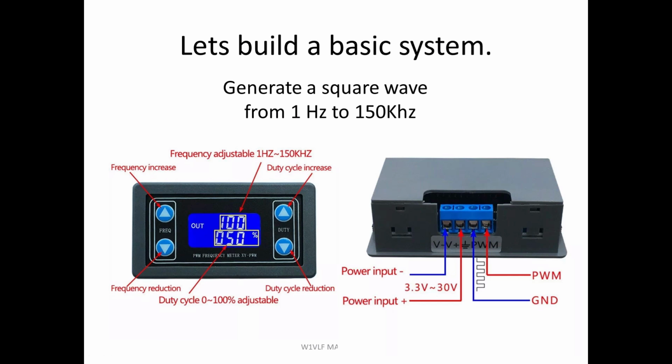So you need a transmitter. Well, you can go on eBay, and for like $5, at least that's what they were back when I was experimenting with this a couple years ago when I first got these, I got these little square wave generators with a variable duty cycle. This moves the frequency up and down. They're adjustable from 1 hertz to 150 kilohertz. They're not crystal controlled, so if you want to use 20 kilohertz, it might be 18 or 19 or 20 or 21. But for this purpose, it's experimenting. It works out really great.